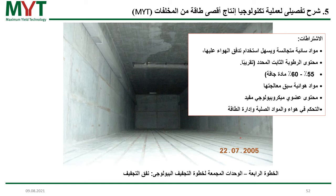But after the mixing, after the presses, the waste has a constant moisture content of approximately 55 to 60%. So this is ideal because it's all homogeneous. And it's an aerobic pre-treated material. This is also extremely important. If you put the waste material into anaerobic digestion, into the fermenters, you are in an anaerobic milieu and you will have different bacteria, different microorganisms. To make the change from anaerobic to aerobic is extremely difficult and takes a lot of time because the microorganisms have to change inside the waste.